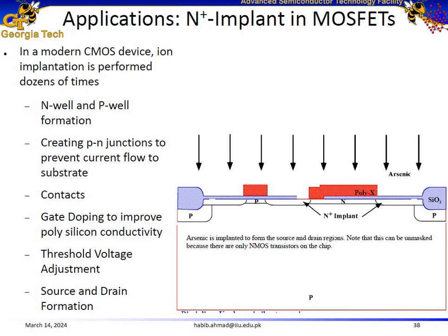And the technology node actually is the distance between the drain and the source. The smaller the technology node or the channel length, the more transistors we can fit on the same size chip. So that's why you see that every newer technology has a shorter channel length, resulting in fitting more transistors on the same size chip,